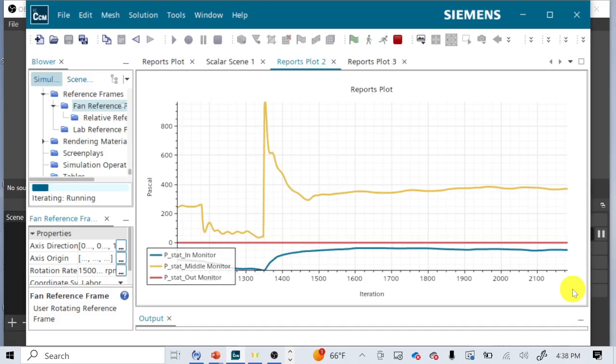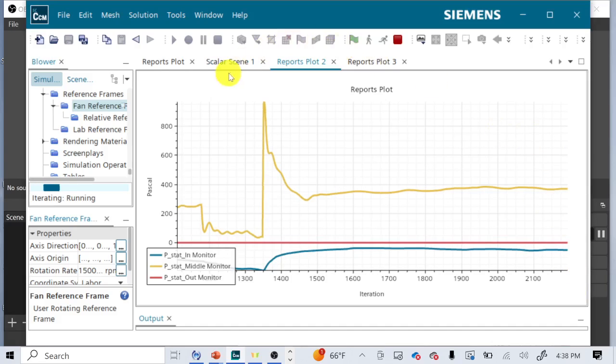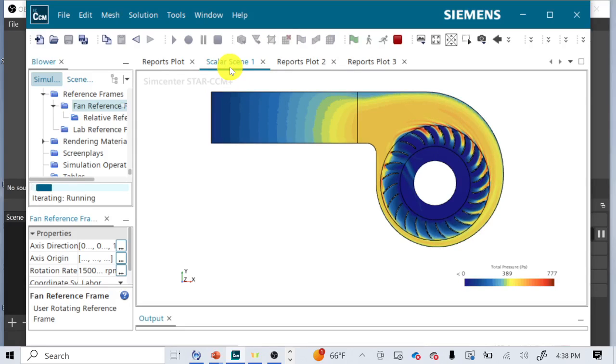So just to put all the pieces together: last week's recording was building this part. This week was all about that part, adding the resistance. And now we have everything to get the results. The resistance is the thing that you're changing. I'm using I to represent inertial resistance. Depending on what the inertial resistance is, you'll get different behaviors of static pressure, total pressure, volumetric flow rate, etc. And you can see the very clear striations as total pressure is dropping through that area of flow resistance. It doesn't quite drop back to zero, but it does drop pretty far.